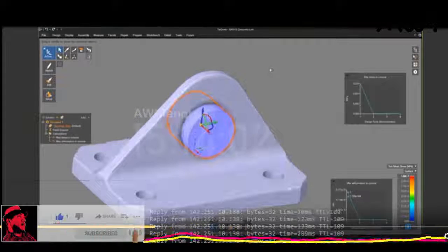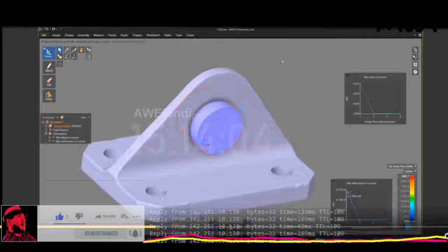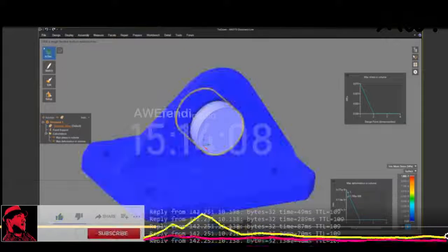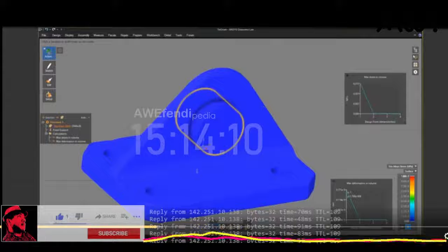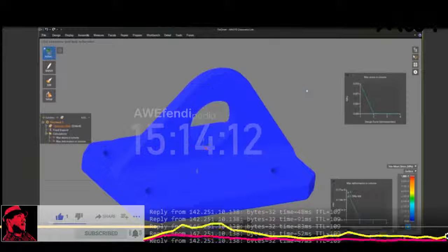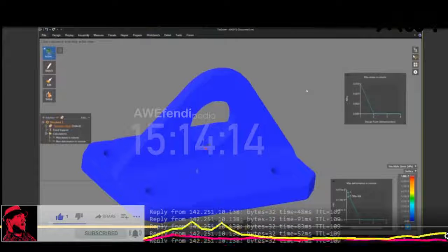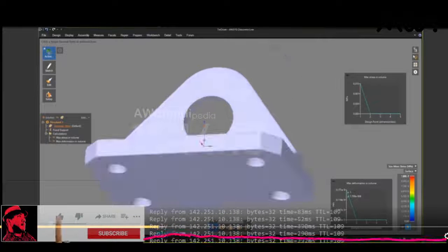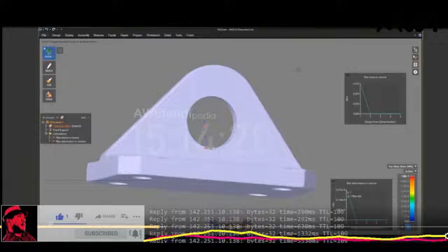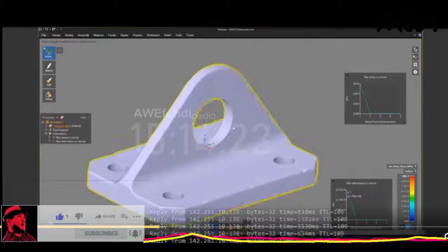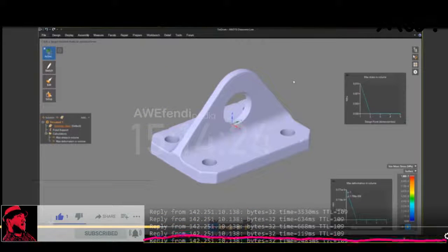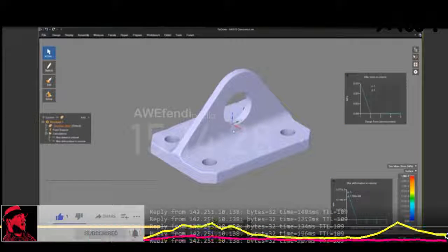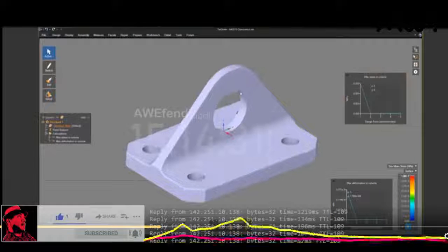Everything has to be dimensioned. I'm not really worried about dimensioning right now. What I want to do is just move the hole to a rough area. If it works, if I see the performance that I want, then I'm going to go choose the CAD tool that I'm comfortable with, whether it's SpaceClaim or Discovery SpaceClaim or any other CAD tool. And so here I've cut out a brand new hole. It's a little lower, and I just want to quickly see if I get low stress and low deformation here. What I should have done is pause that so we don't get this false kind of reading.